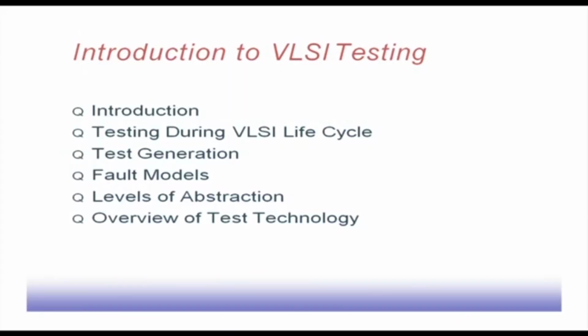So, we may get the entire PCB on a single chip, giving rise to system on chip type of architecture. So, that way, at which level we are attacking these faults, at which level we are trying to address this fault, that gives rise to these levels of abstraction. So, it may be easy to attack the system behavior related faults at a much higher level compared to, say, at transistor level, whereas when we are talking about, say, individual lines being short or individual lines being open, it may be better that we talk at a much lower level.